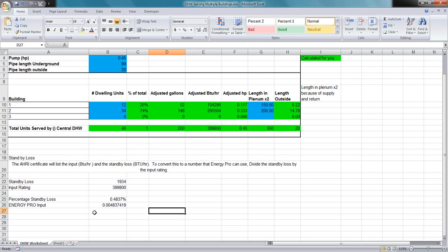within the water. When the hot water is just sitting in a storage tank, it's going to be releasing some of that heat just based on how well it's insulated and what the temperature is of the space around it. So you can think about it in a system that has a boiler and a tank separate from one another. Those are the two measures of efficiency we're looking at. The standby loss dictates the efficiency of the tank, and the recovery efficiency or the thermal efficiency dictates the performance of the boiler.